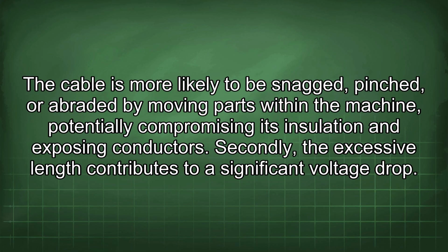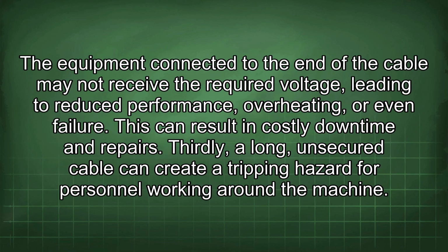The cable is more likely to be snagged, pinched, or abraded by moving parts within the machine, potentially compromising its insulation and exposing conductors. Secondly, the excessive length contributes to a significant voltage drop. The equipment connected to the end of the cable may not receive the required voltage, leading to reduced performance, overheating, or even failure. This can result in costly downtime and repairs.